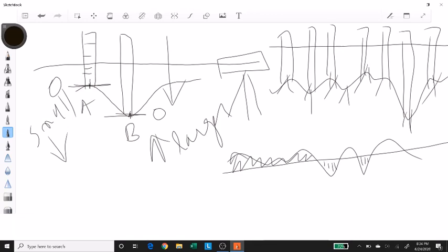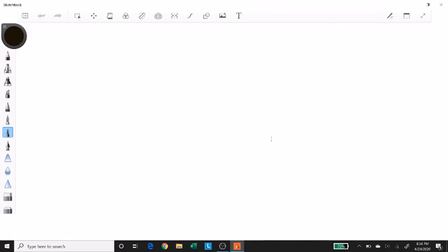So that really economizes the project, and that is how you can use leveling as a very powerful tool to execute your projects. Similarly, whenever we construct roads at a grade, or water supply lines or sewerage lines, they have to be at a specific grade or a slope, so that naturally the liquid inside can keep on flowing at a speed that you decide on depending on the slope.